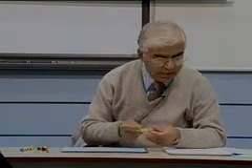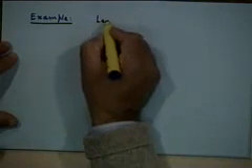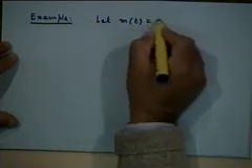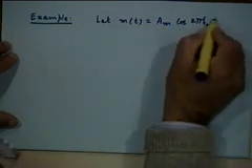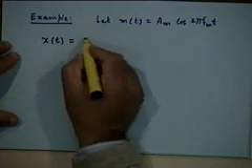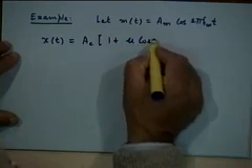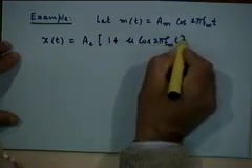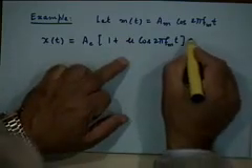Okay, to wind up the discussion on amplitude modulation, we'll take up a small example. Let's say our message signal is a pure sinusoidal signal of frequency f sub m. So that your modulated signal x of t is given by, what will it be given by? Something like this, right? 1 plus mu times the message waveform m of t into the carrier,